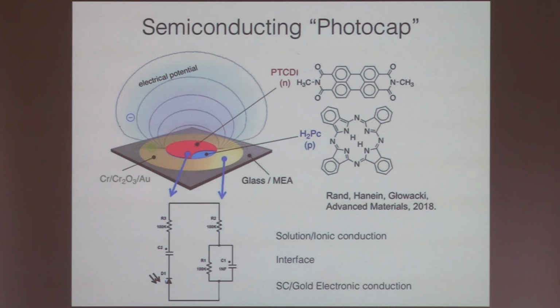The thing is that silicon is not a very good material in these settings for many reasons. Probably the most important one, which people don't often appreciate, is that in wet conditions it's extremely unstable. I never could understand how silicon nanowire devices can even work. These things just come off in no time. So silicon devices must be passivated, which is counterintuitive.